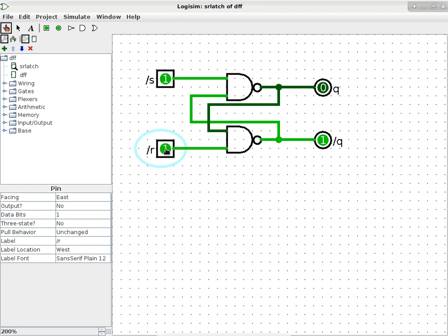Okay, so let's just go through this in our minds and imagine what's going to happen. I cannot actually simulate this, but I can explain it. So imagine that both input pins switch from 0 to 1 at exactly the same moment. Then one of the inputs to both NAND gates will go from a 1 to a 0 as a result. No big deal. But it takes a certain amount of time before that change affects the output of the two NAND gates. That is the key. After some nanoseconds, both gates will change at the same time. So both gates will update their outputs to be 1s.